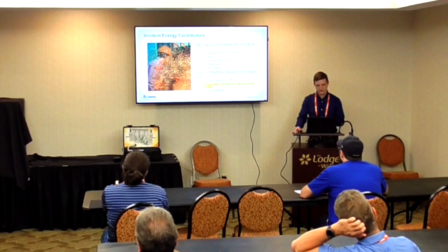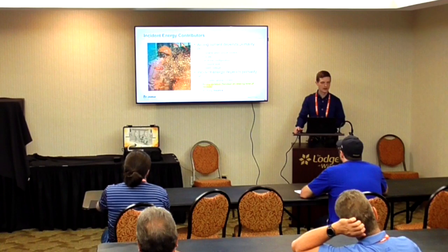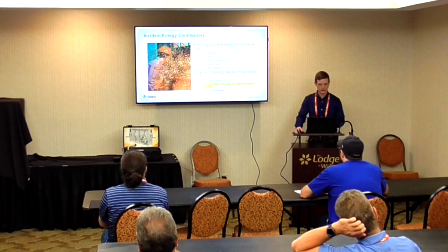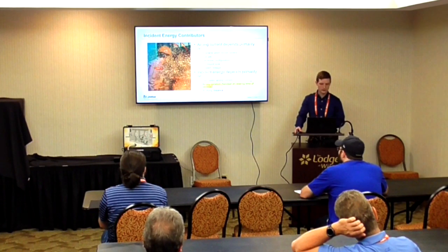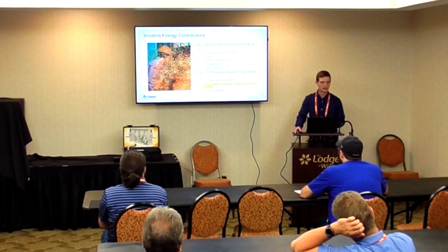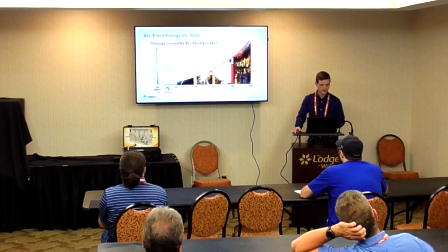Just before I move on, because the next slide is relevant to this, the first thing that we can actually do about arc flashes is typically going to be this arc duration, which is why I have it highlighted here. You can see some of the other factors can actually be adjusted during the design phase. But once you are actually in the application, most arc flash mitigation methods try to interrupt as fast as possible to reduce against this.